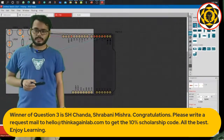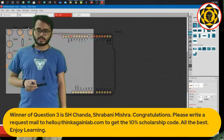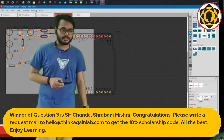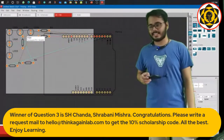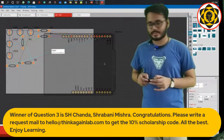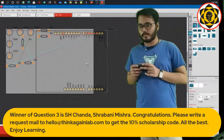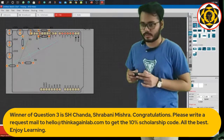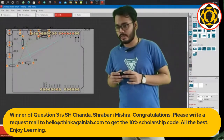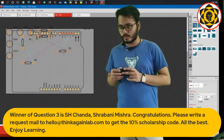See, a little bit before this thing was not configured at all, but now look at it. Everything is configured in here. Everything is connected by these transparent lines. These are transparent because we have not routed them yet. So the technique that I showed you guys a little bit earlier in that schematic, same stuff. Basically, we put the resistors, we put the LEDs, and then we finally auto route.